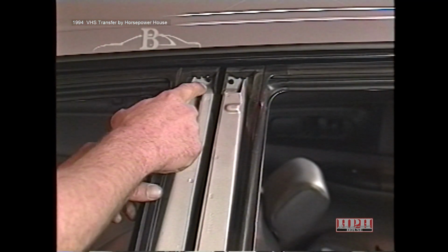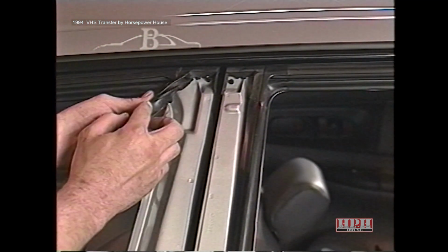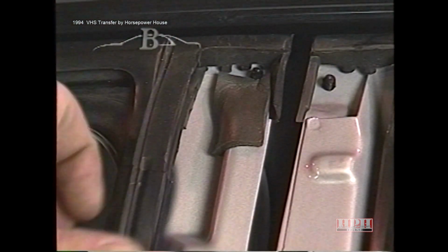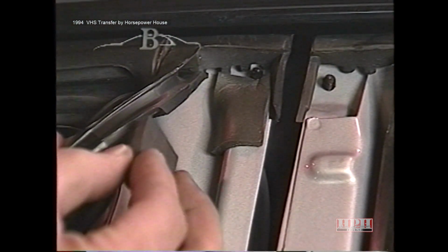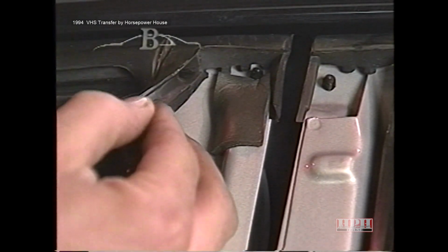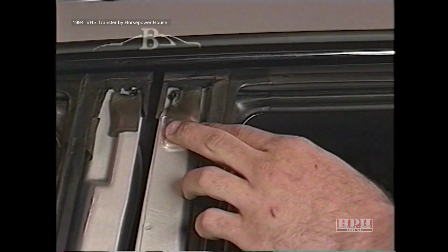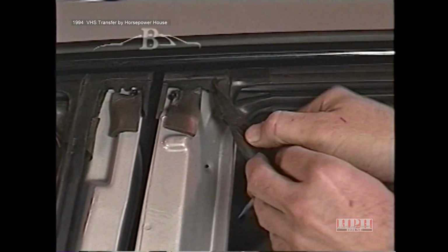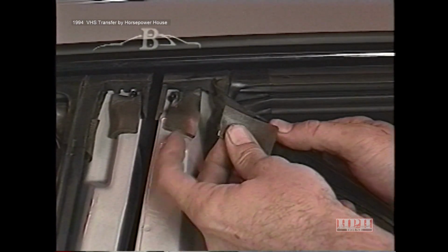Traffic noise can also come from an opening in the rear of the front door, similar to the opening at the front of the door at the inner panel. Again, cover this opening with foam tape. Additionally, similar openings may exist on the rear doors. If they are present, cover them with foam tape.